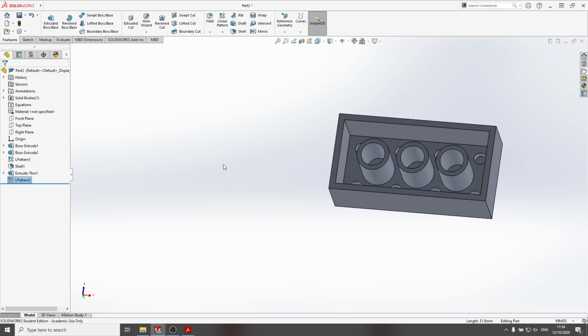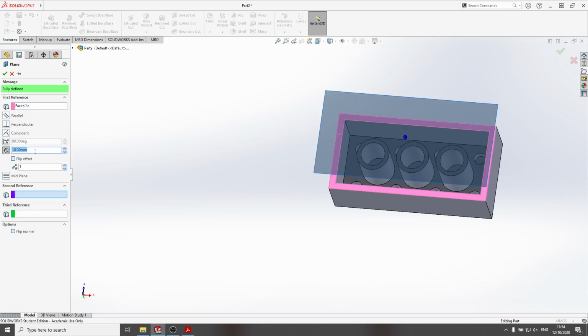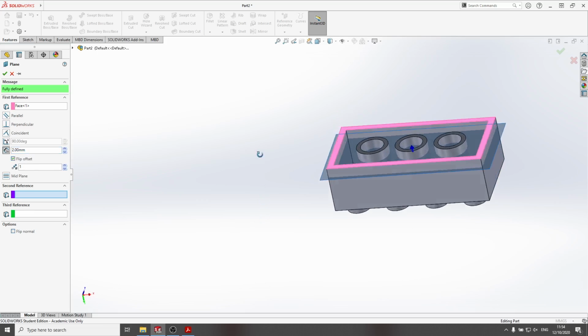And the easiest way to do that is to create an additional auxiliary reference by saying I want to include a reference geometry plane, and the first reference for the definition of the new plane is that part, and the distance is 2 millimeters, and I want to have it in the other direction.